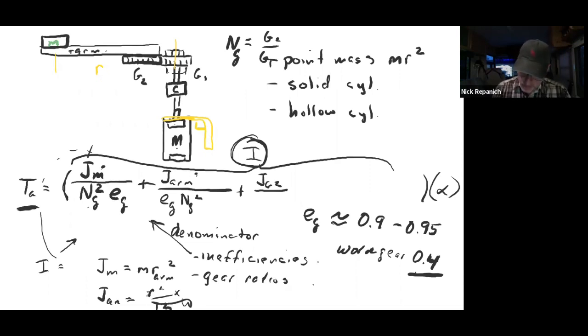And well, wait a minute, what do we do here? Inertia of that gear. Well, in order to get from that gear to that gear, you've got to do the ninja jump, right? That means that for gear 2 to turn, it turns after an inefficiency. So therefore, it turns after the gear ratio, doesn't it? We go across the gear ratio. Just what? NG squared. Huh, there's another one of those. Same exact. Okay. This is how you find out. And then J of the shaft.